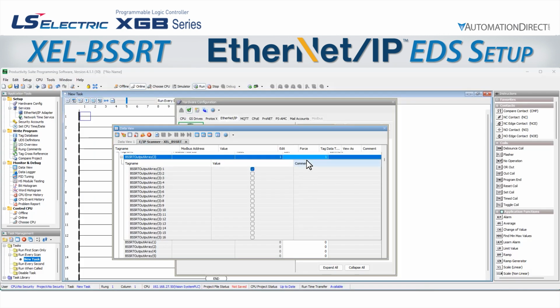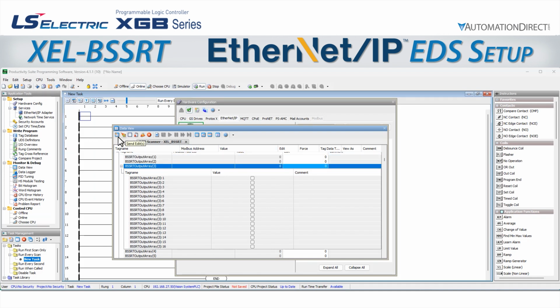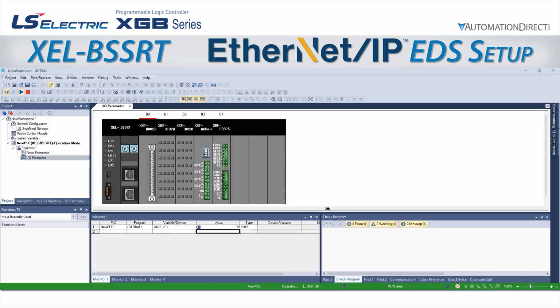Let's go back to Productivity Suite and turn that bit back off by writing a 0 to the word, and back to XG5000, and the point is back off. Perfect. Reading information would be the same process, but with the input words. We are now able to control our remote I/O with our Productivity PLC using the EDS file generator in XG5000.